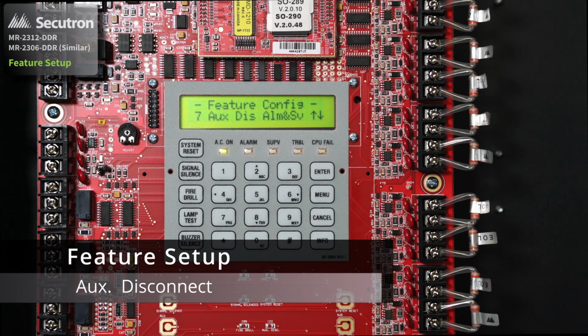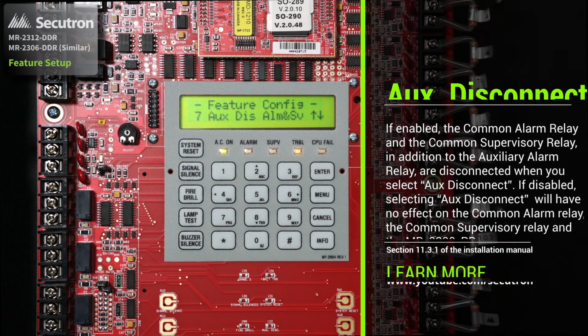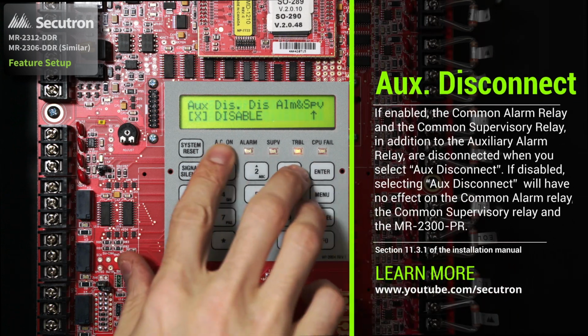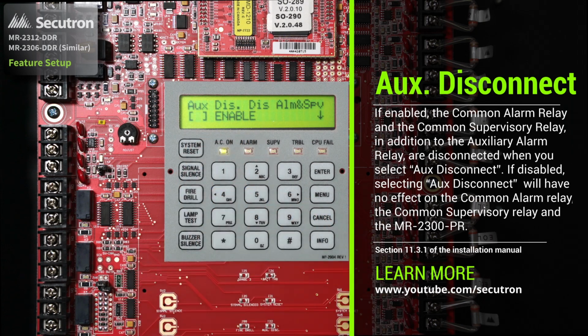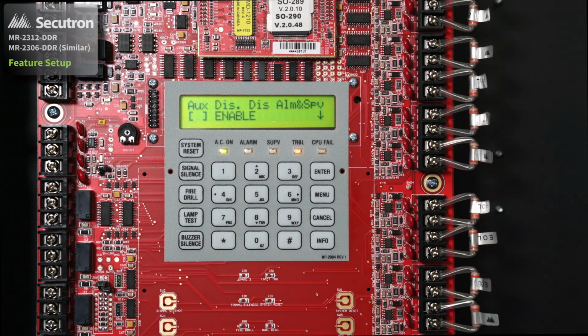The next feature is our aux disconnect, which disconnects common alarm relay and common supervisory relays. If we select Enter, by default it has been disabled. You can press the up cursor to enable it. If enabled, the common alarm relay and common supervisory relay, in addition to the aux alarm relay, are disconnected when you select aux disconnect. The MR-2300 series will not transmit a supervisory or alarm event. If disabled, selecting aux disconnect will have no effect on the common alarm relay and the common supervisory relay of the MR-2300 series panel.